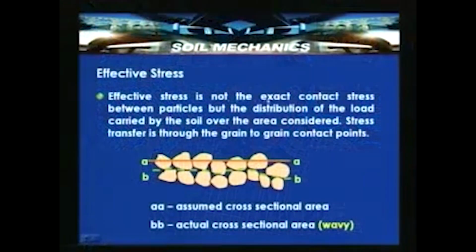So, what we discussed in this slide is that effective stress is not the exact contact stress between the particles, but the distribution of the load carried by the soil or the area considered. Stress transfer is through the grain to grain contact points.